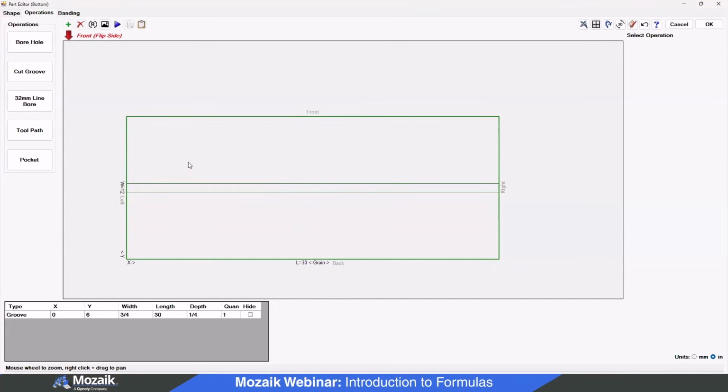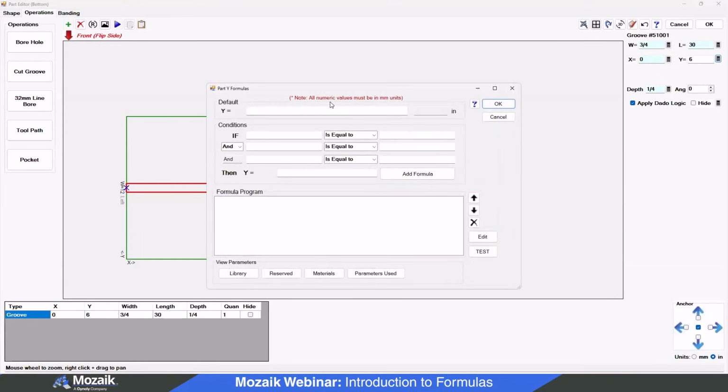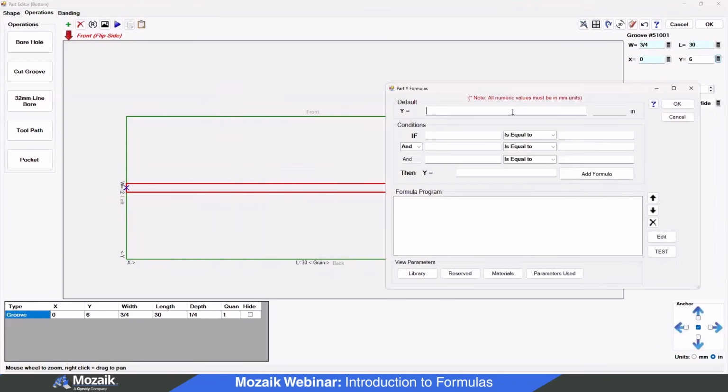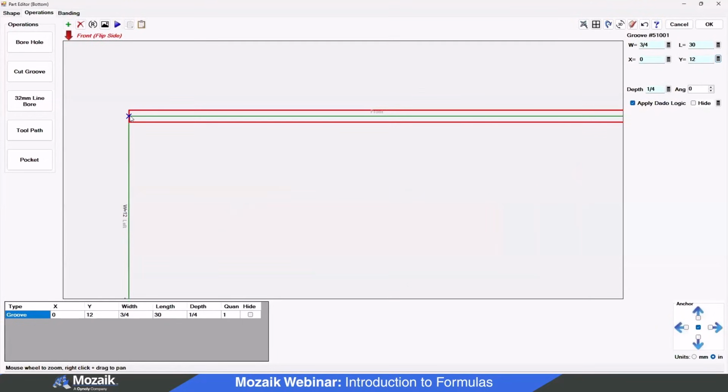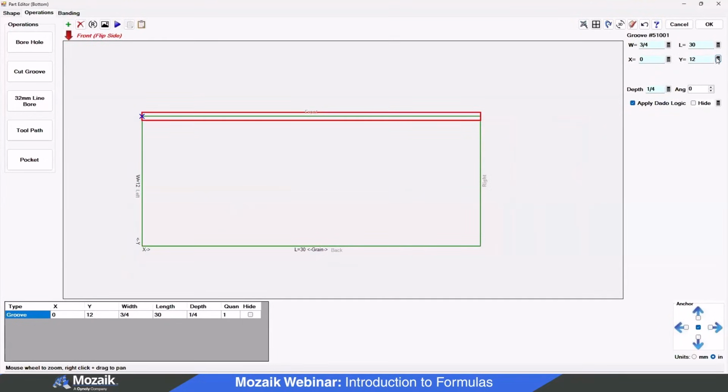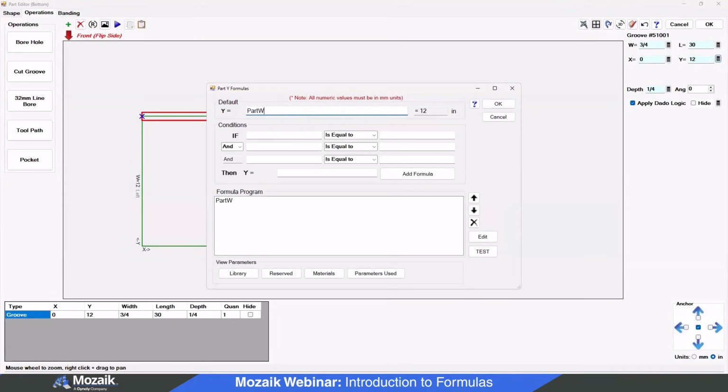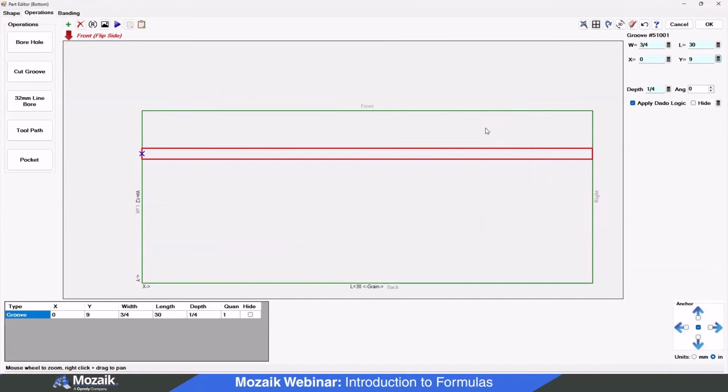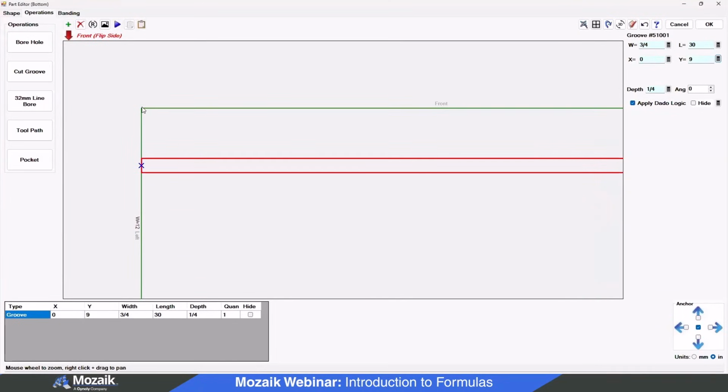Now we have to think about the positioning. So this is the front. So we're looking at the underside of this panel. So it's the front over here. So let's go into our Y. And I want to say part length, so sorry, part width. We want to go across the width of the part. If I just put part width and say, okay, our dado is now locked to the edge, because remember, it's working on center. Now I want to go back that recess. So I'm going to say part width minus light groove recess. We'll say, okay. But so that's set to 3 inches. Remember, we set that to 3 inches, but it's 3 inches from the edge of our part to the center of the dado. I want that clearance to be 3 inches here and then that light groove.